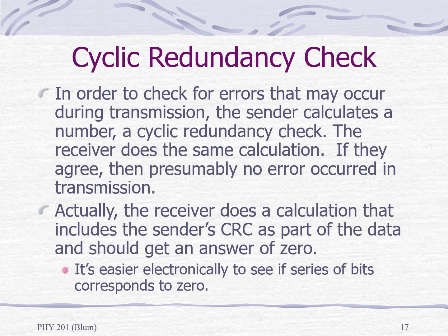A cyclic redundancy check, or CRC, is done in conjunction with a transmission. So you already have the shift register that's in the modem, both in the sender and in the receiver, but you add some additional functionality to it to do an error correction scheme. So the sender will do some calculation based on the data being transmitted, and the receiver will do basically the same calculation. And if they agree on the answer, then presumably no error occurred in the transmission, or at least it's less likely that some error occurred in the transmission.